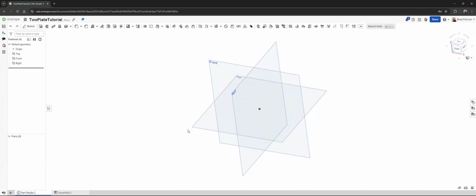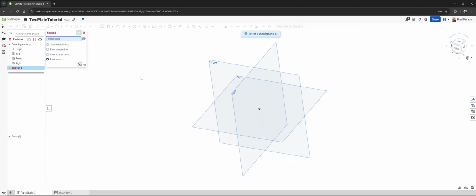I would start by selecting our top plane and creating an extrude. So faces and sketches. It wants a sketch first, so I'm going to go ahead and close out of that. That's okay. SolidWorks would allow us to create the sketch in the extrude, but in another workflow, you can sketch in SolidWorks first and then create your extrusion or revolve or that kind of thing. So it's not a deal breaker so far.